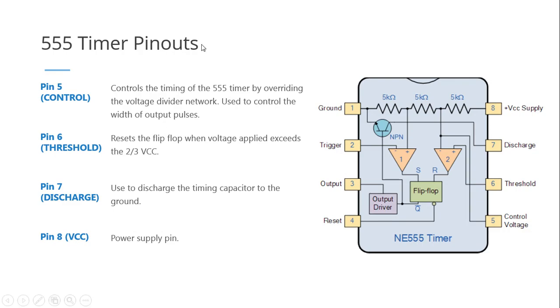Pin 5 is a control circuit. Now, the output waveform at output pin 3 has an output that goes high to low once, or can be controlled by the trigger if it's a bistable circuit, or a continuous stream of a square wave, high and low output.